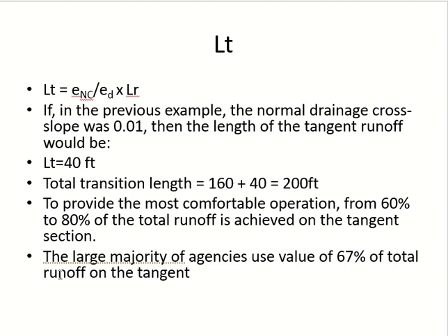Okay. Now, at which type of location do we provide super elevation? Ramps, roundabouts. Curves. Yes, curves. You may not give super elevation at roundabouts. But on curves, on highways, it's required. So the super elevation is required on the curves. Already explained, we have to cancel out the centripetal force, so we need super elevation on the curves.